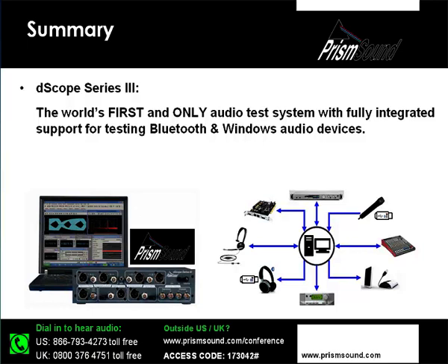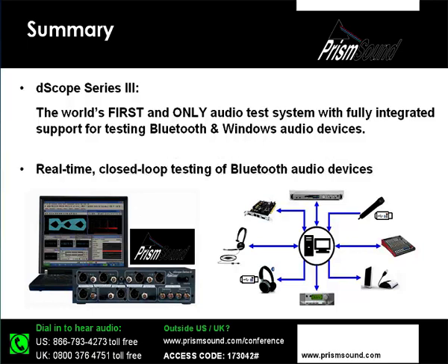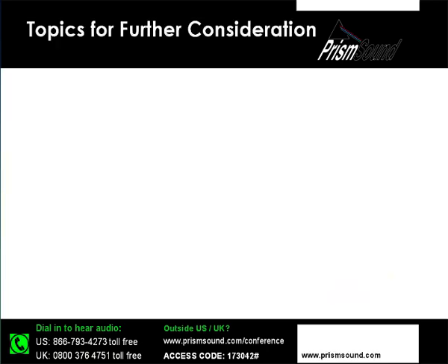We looked at the sound card I/O functionality, which allows us to directly address Bluetooth and other Windows audio devices connected to our host PC, and this importantly allows us to make real-time closed-loop measurements of Bluetooth and other Windows audio devices, negating the need for any external signal generation software or offline analysis of WAV files. So this is a very powerful feature that I hope we have illustrated to you here today.